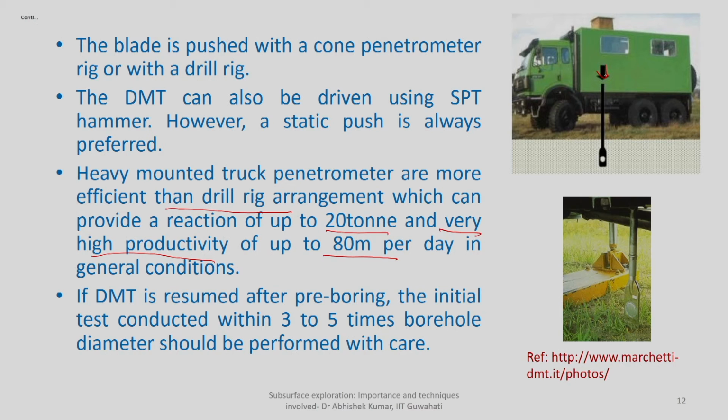That's how you mount your dilatometer on the truck, which acts as a reaction frame. The second one shows the dilatometer in contact with the blade, the blade is in contact with the soil, and depending upon the reaction generated, you push it into the soil. So the reaction required to push it into the soil and the pressure required to inflate or deflate the membrane come from two different sources.